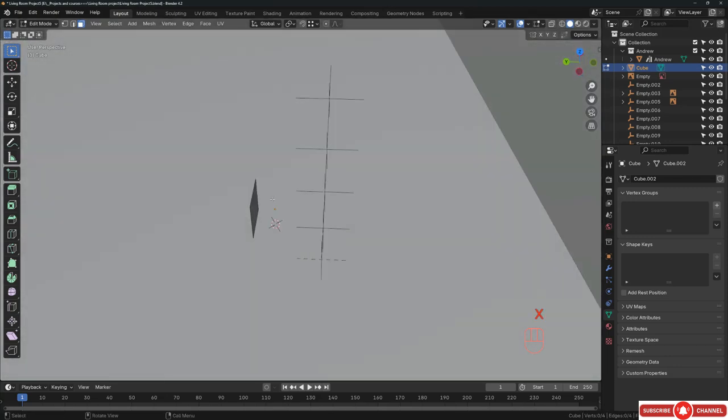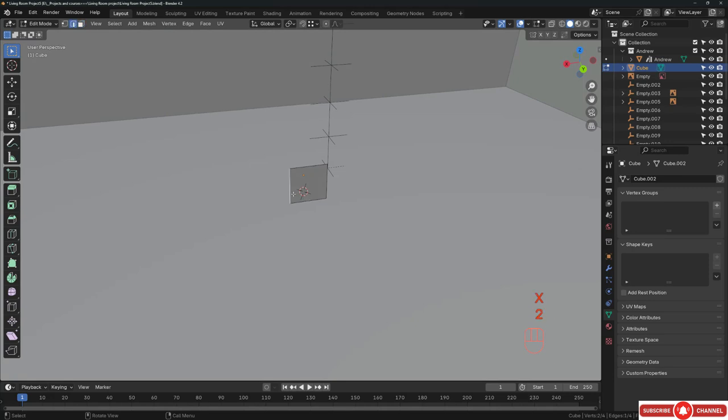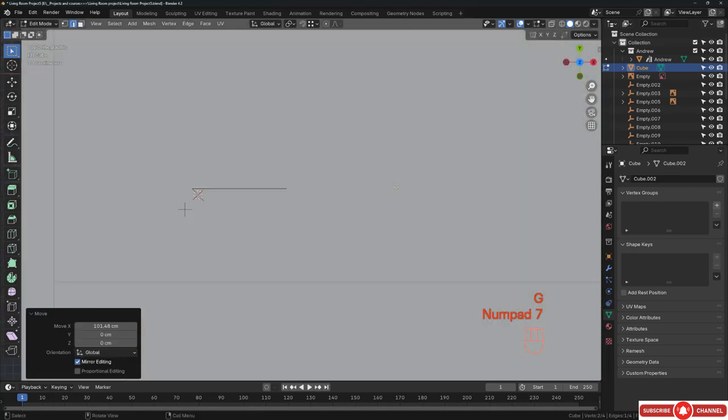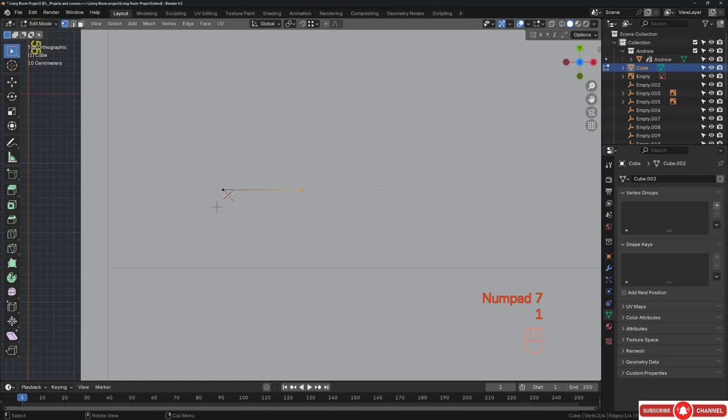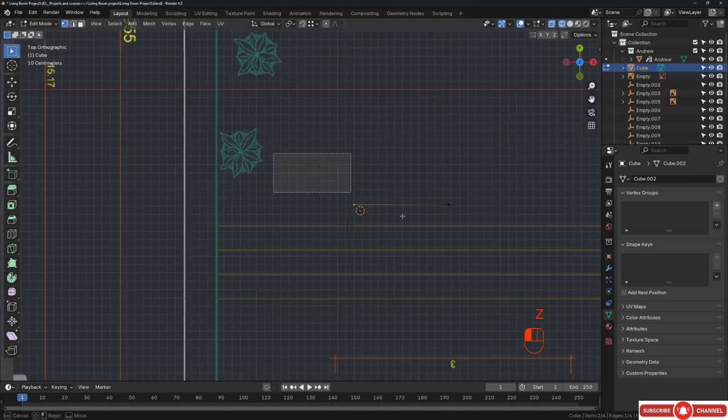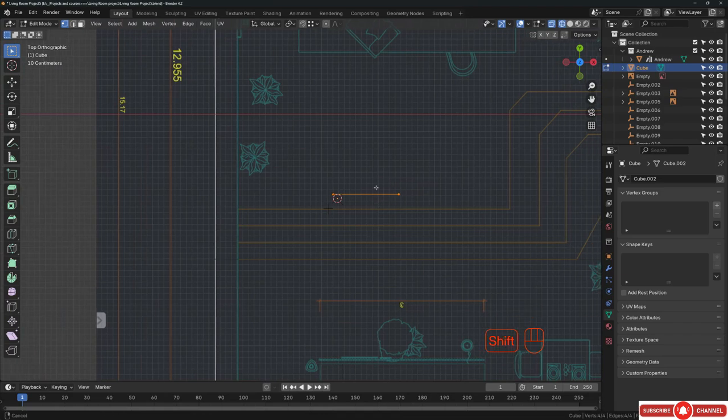And yeah, this one as well, I don't want it. And let's use this edge. You can just push it a little bit, and now we have something. Let's go to the top, go to vertex selection mode to see better. Hit Z to go to wireframe, and now let's start with these.